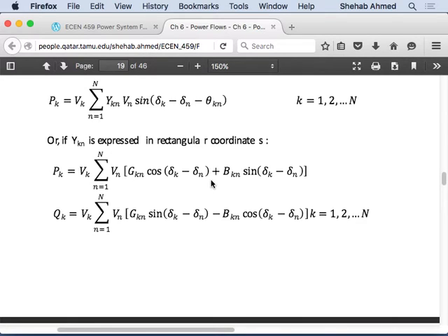Okay, but what is a good estimate to start with, based on what we know about the per unit system? What is a good estimate to start with for voltage magnitudes and angles for an unstressed system? Exactly. For an unstressed system, voltage magnitudes are all around 1. And for angle differences between buses, in an unstressed system, meaning there is not a huge amount of power flowing, the angle differences are also very close to 0.